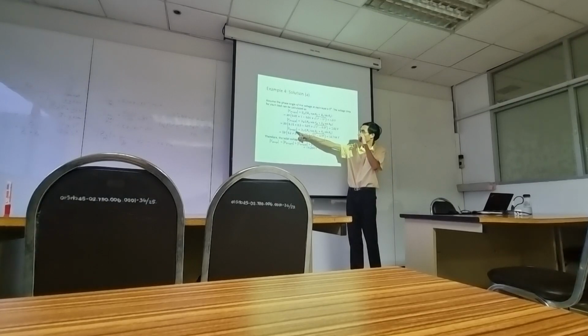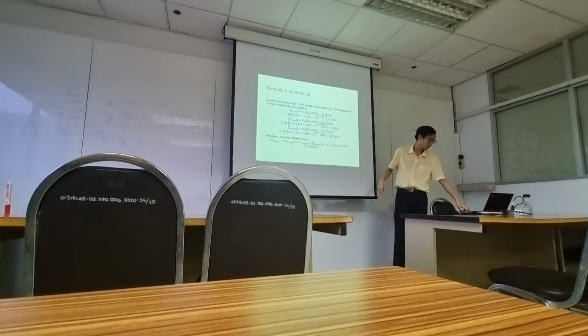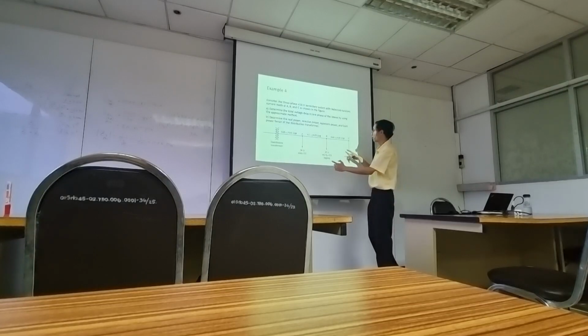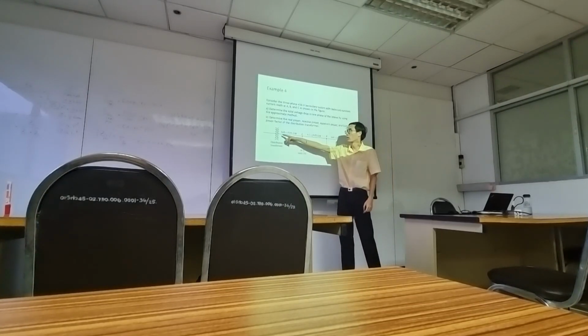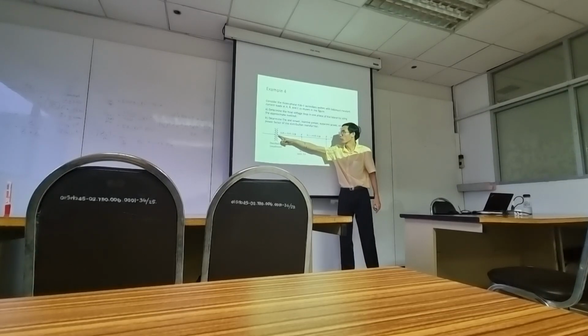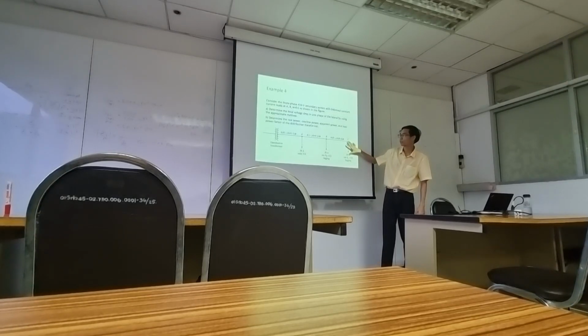Voltage drop due to load C is the same, but this time RC and XC, you have to include from the transformer to here, because the load is located here.